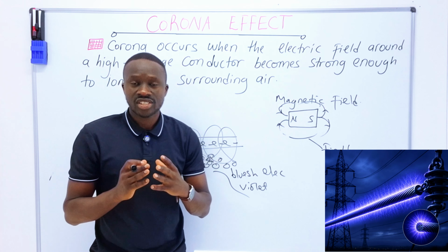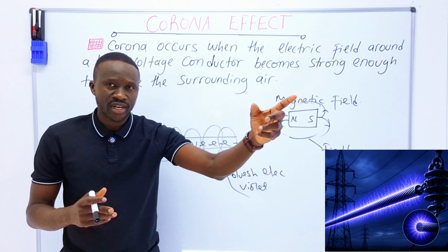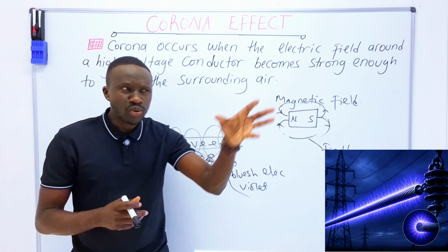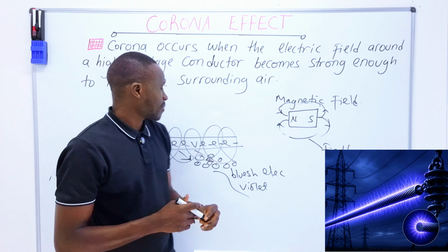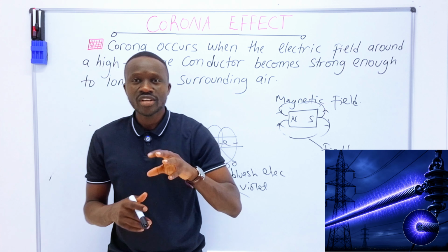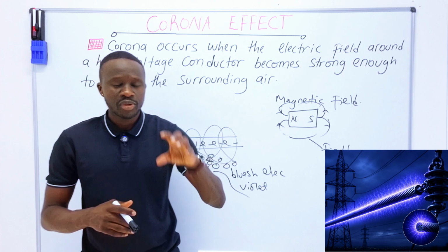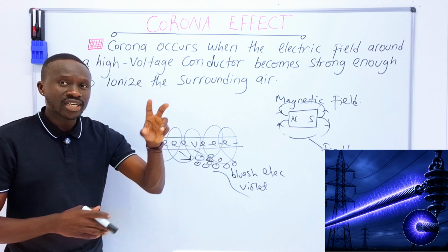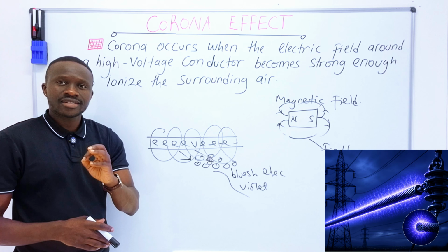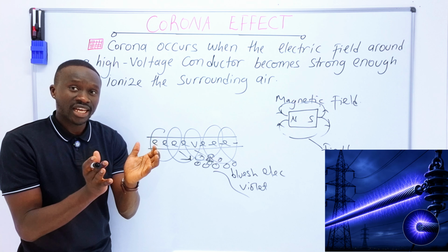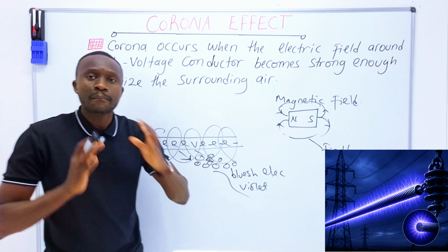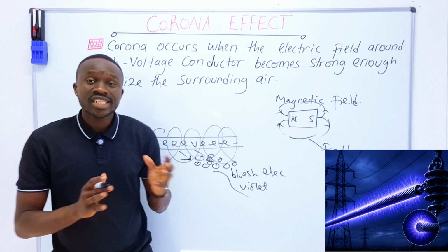Take note and observe this sound. And once you observe very well, you may see that electricity, which is bluish, with that sound, and that is the corona effect. I never wanted to leave this behind in the transmission lines, because this thing happens only on high voltage transmission conductors. This topic is in the transmission lines, still in transmission, though we are about to leave them. But I didn't want to leave this behind, so that you need to know, because this is a daily thing.